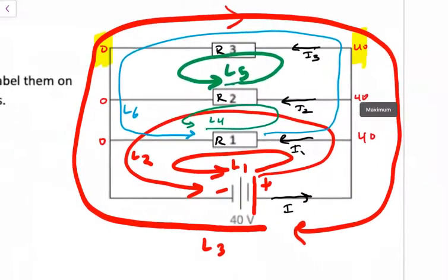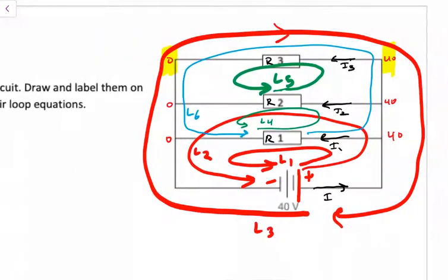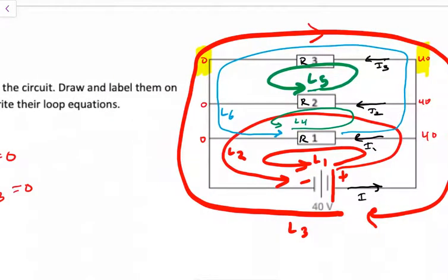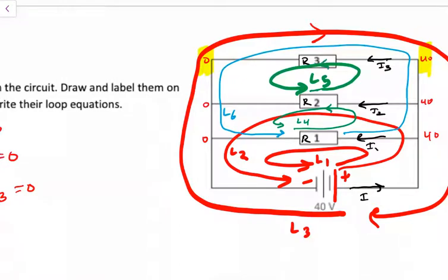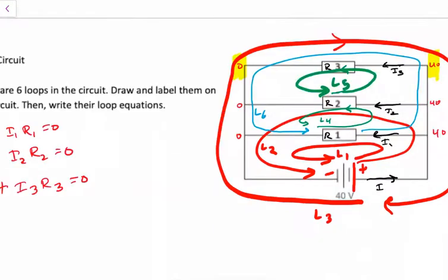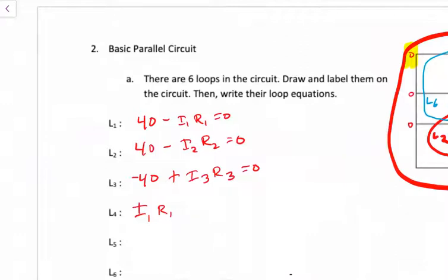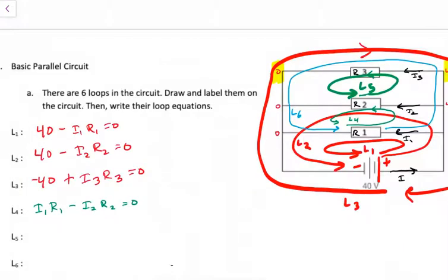And then as I'm passing across resistor 2, right, because my loop is this. That's my loop. As I'm passing across resistor 2, I'm going in the same direction as the current. Right, here's my loop. Therefore, I'm going from high potential to low potential, so I'm losing I2 R2. Let's do this in green. Minus I2 R2 is 0. And this is just stating that the voltage across each branch is constant, such as in parallel circuits.